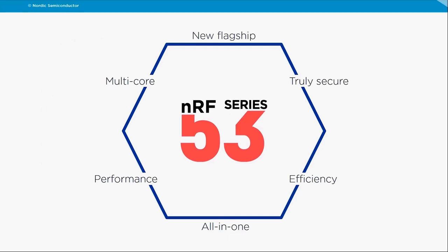It's an all-in-one device, so it takes all the great features from the nRF52 series, the Bluetooth 5.2 support, Thread and Zigbee. It's capable of operating at 105 degrees, and can do the extended supply range, 1.7 to 5.5 volts. But it's also adding more performance, efficiency, and higher integration, while also minimizing the power consumption.